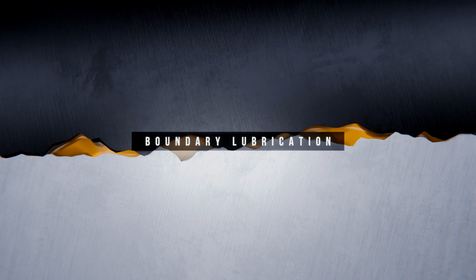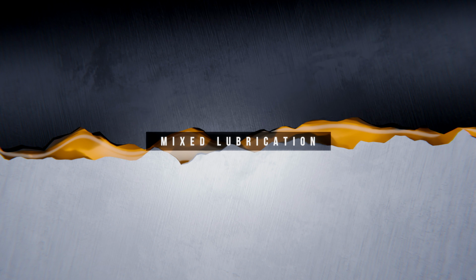The thickness of the lubricating film has a big impact on friction. When it's very thin, surface asperities still make contact, and although friction is reduced compared to dry contact, it remains relatively high. This is known as boundary lubrication. As the film thickens, a growing portion of the load is supported by the fluid. This is mixed lubrication. And if the film thickness continues to increase, it becomes thick enough to completely separate the surfaces, which is hydrodynamic lubrication.